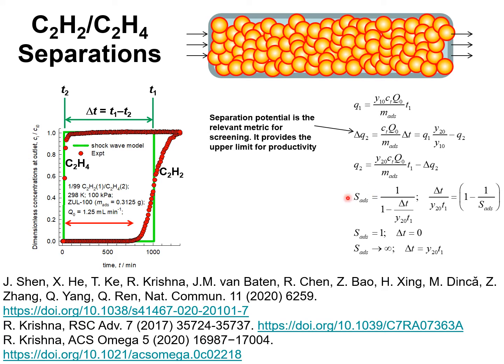The adsorption selectivity is related to the delta time, delta T, determined from the Shockwave model by this expression. And from the selectivity expression, we can interrelate delta T, the time interval between the breakthroughs of component 2 and component 1, with the selectivity.